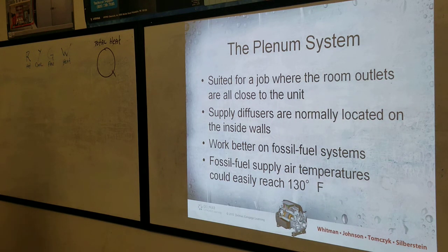The plenum system, suited for a job where the room outlets are all close to the unit. Supply diffusers are located on the sidewall. Work better on fossil fuel system. Fossil fuel supply air temperature could easily reach 130 Fahrenheit.